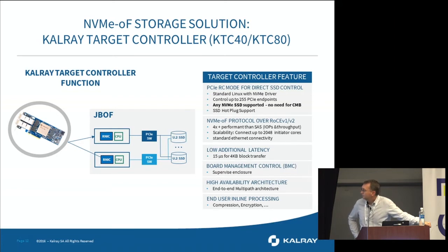In terms of latency, today we can achieve up to 15 microseconds wire-to-wire latency for a 4 kilobyte block transfer. Meaning it's a relatively low added latency compared to the average latency that you have on the SSD side. Board management control, you can support inband or out-of-band board management. That is end-user dependent.